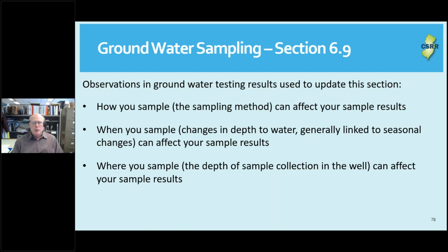We are talking about the interaction of variables such as the site hydraulic gradient, is it upward or downward, and how strong is the gradient? The solubility and density of the contaminants of concern. Are we looking at L-NAPLs or D-NAPLs, or just dissolved phase concentrations? And changes in permeability of the aquifer material, both vertically and horizontally. Are there restrictive layers or dominant bedrock fractures that are affecting contaminant migration? In simpler terms, these observations are likely due to the spatial relationship of the well intake interval to the groundwater plume. Next slide, please.